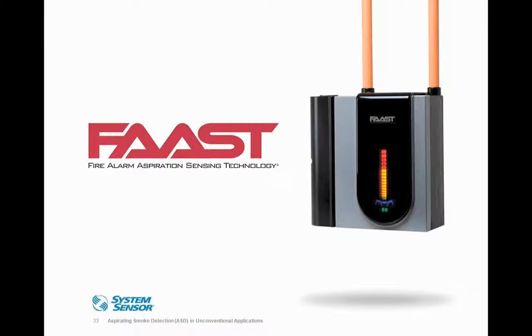Yeah, absolutely. Again, these frequently asked questions we get are just the most common. There are other applications, but yes, in an area like that, you probably have the issue of high ceilings as well as condensation. So we talked about the condensation. You can have the detector drip loops to catch that. High areas, we recommend ceiling protection across the ceiling, but in these high ceiling applications we also recommend side protection on the side walls.